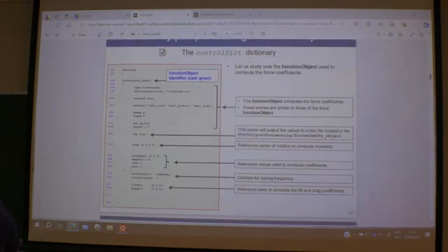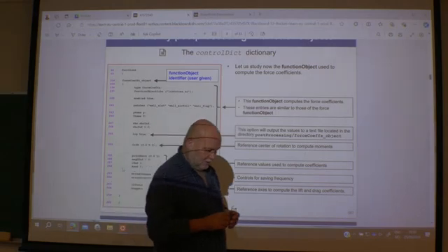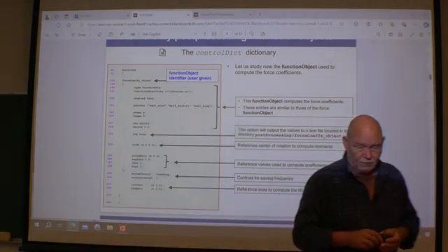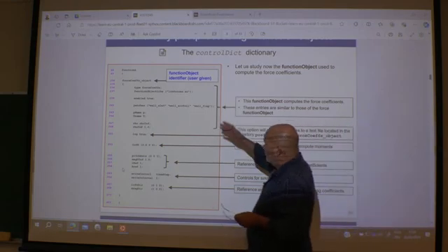And if you go to the force coefficients, this is something we are going to use. The force coefficients are just the non-dimensional forces. You will have lift and drag. Drag in the direction you specify, and the lift typically in the cross-stream direction. And it's more or less the same setup.